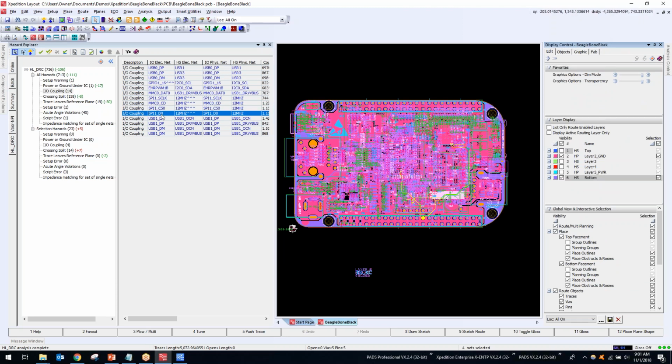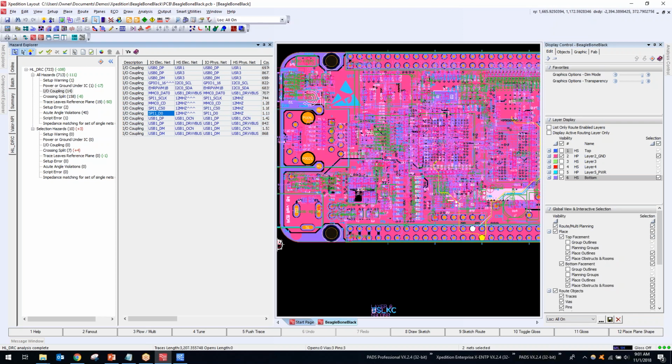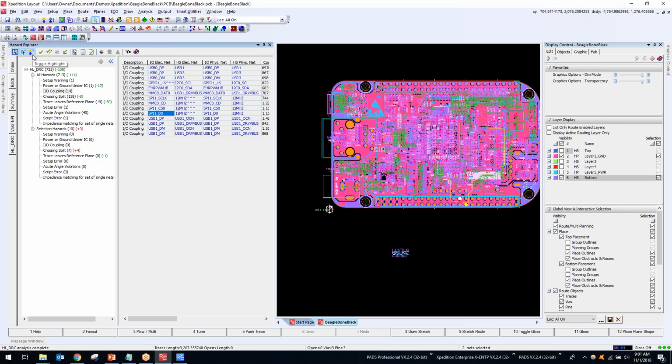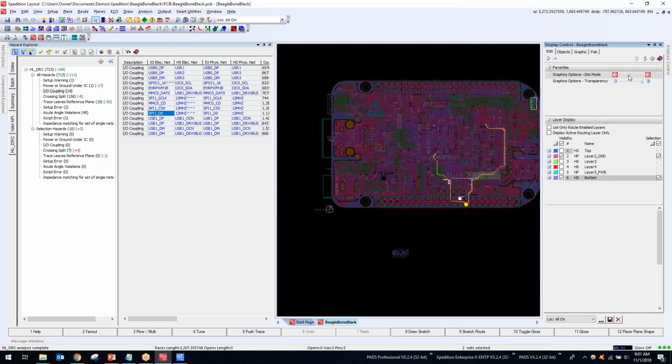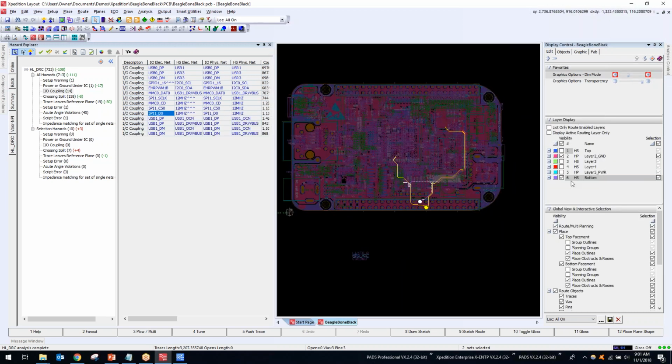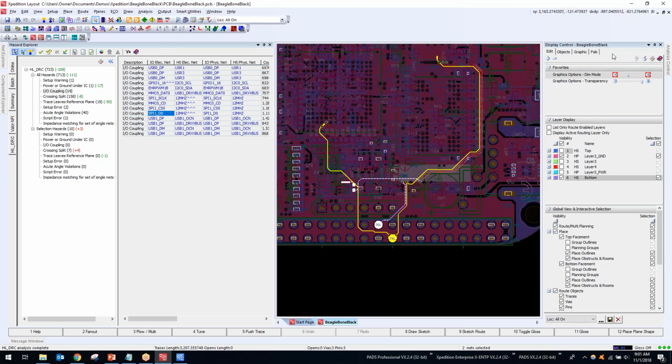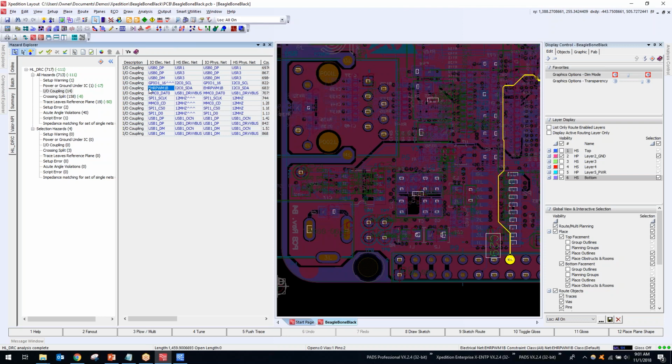If I have my different net selected from the Hazard Explorer and I turn on highlighting in the Hazard Explorer, so you'll see in my icon I can toggle a highlight, and if I have something highlighted I can dim everything else that's not highlighted in this design. All right, so very easy. I can highlight that directly from the Hazard Explorer and then use this dim mode option to dim everything that's not been highlighted. This very easily allows us to identify what happened, where that error is, and hopefully identify a solution for it very easily.